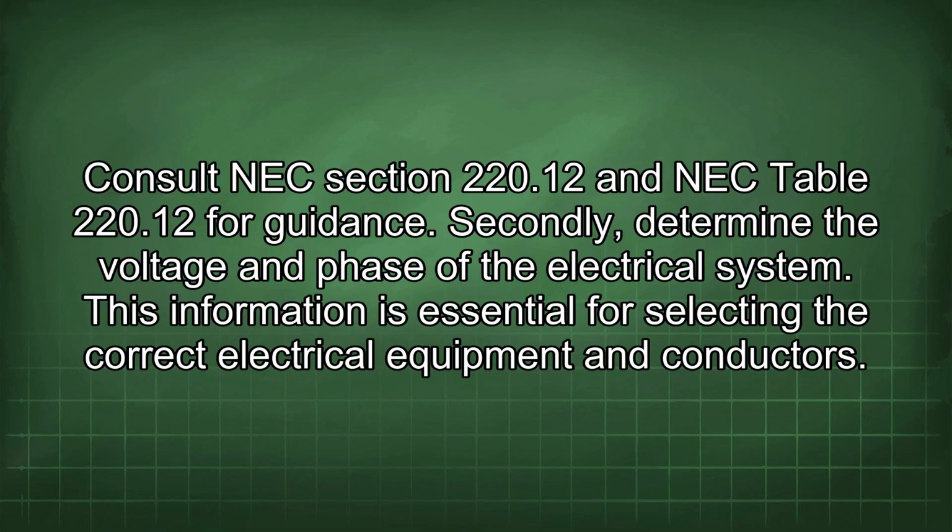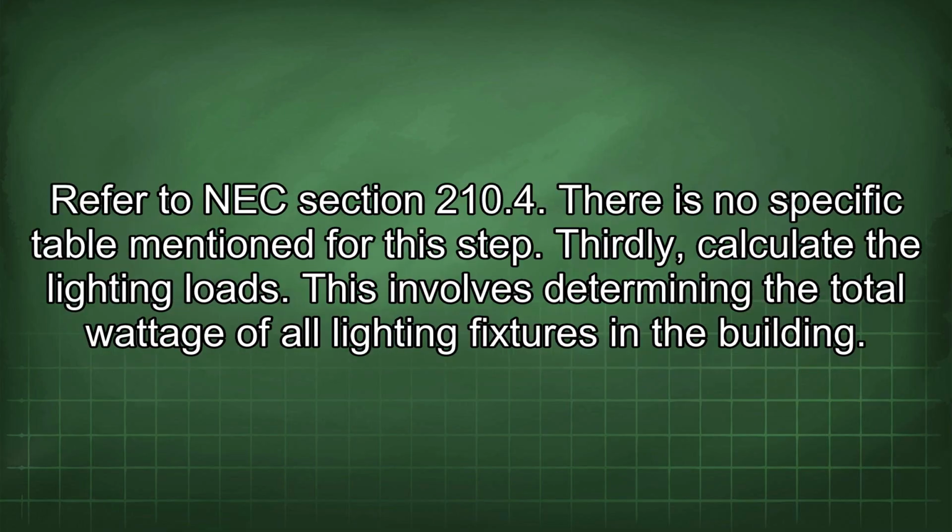Secondly, determine the voltage and phase of the electrical system. This information is essential for selecting the correct electrical equipment and conductors. Refer to NEC Section 210.4. There is no specific table mentioned for this step.